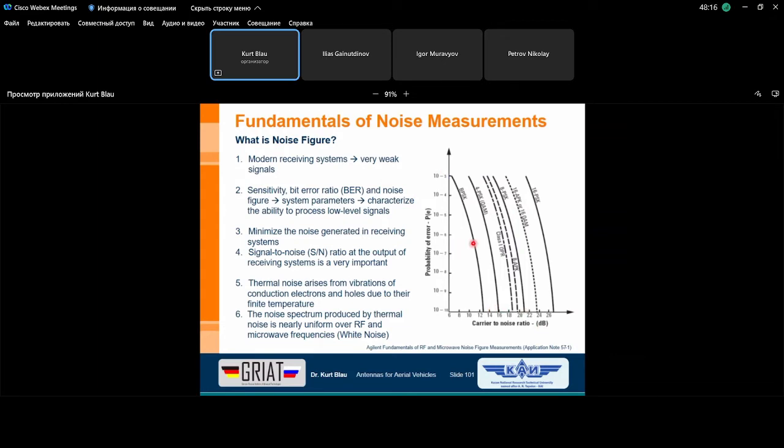For this very primitive modulation scheme, 2 different phase states, switching between minus 90 and plus 90 degree, then for this error rate of 1 in a million, we need a carrier to noise ratio of only nearly 12 dB. For the higher schemes, for the same probability of error, we need much higher signal or carrier to noise ratio.